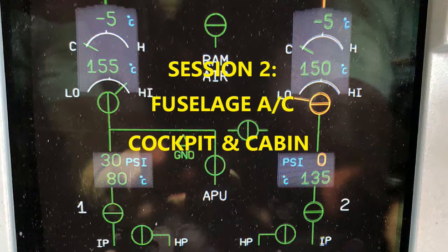Okay, so let's suppose there's a loss of a pack controller. If there is, the anti-ice valves control the pack outlet temperature. So it's kind of interesting. We have a zone controller that's the main controller, and it has two computers on top of that. So let's say that fails, and we have the pack controller. If for some reason there's a failure of the pack controller, the anti-ice valves are going to take over controlling that outlet temperature. Because remember, the most important thing is what's coming out of it, right? Because that's what's going to the cabin and cockpit. So that's what it's going to do. It's also going to adjust the quantity of that hot bleed air that's added to the air cycle machine outlets.